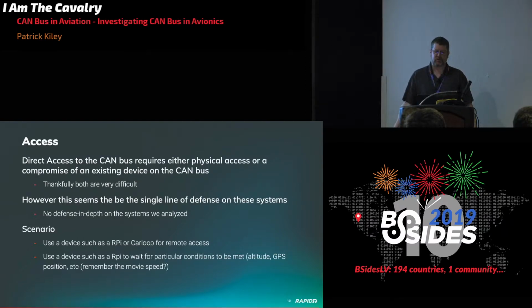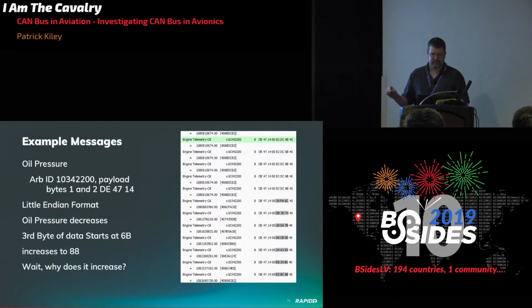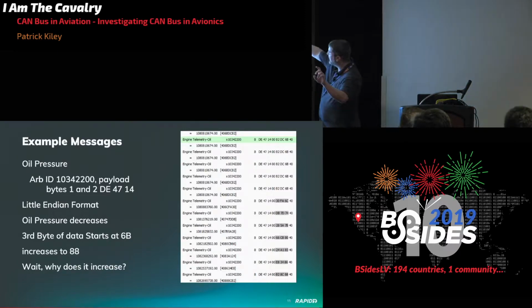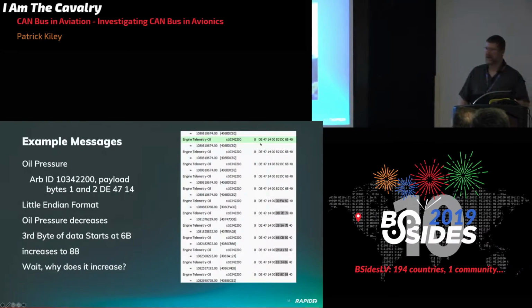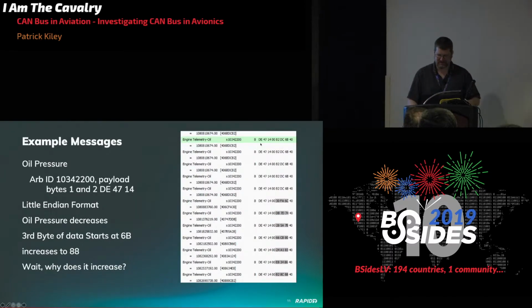A nominal oil pressure for the system was the data, the second half of this message. The first part that you see, the B2, is static, and then you can see it change here later, as I switch the message and switch the message down. If you notice, the number is going up. This is the most significant byte, and you can see it's going 60, 74, 7B. So the number's increasing, but the oil pressure is actually decreasing. And why is it going backwards? This is my one and only joke on this, and I'll skip this. Because it's backwards. It was set up that way.